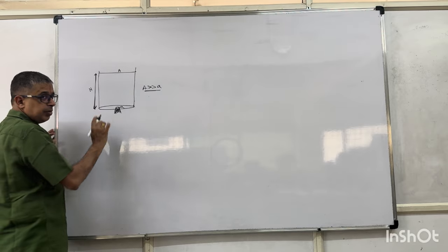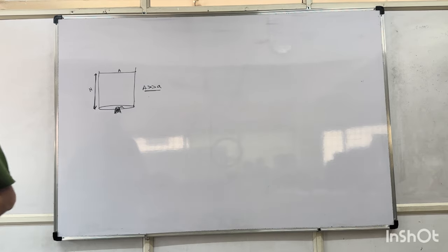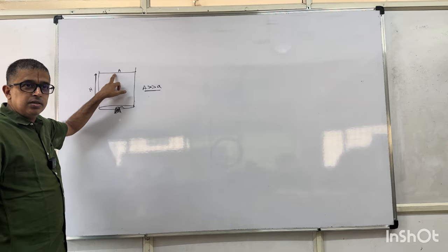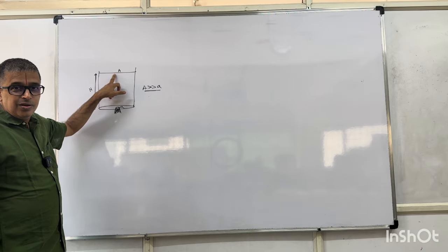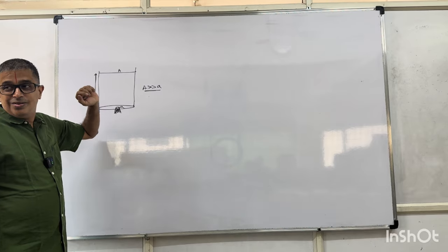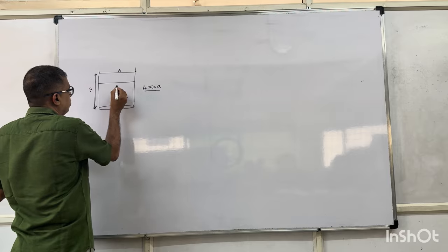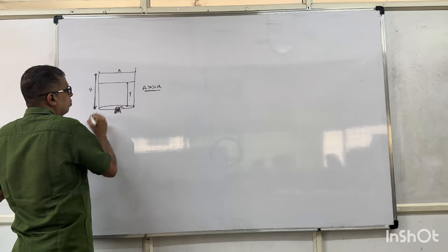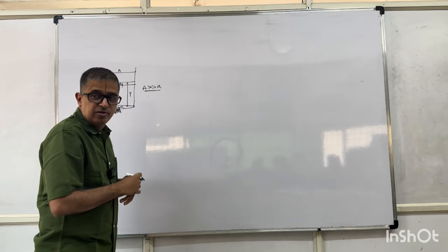That means velocity will be root over of 2gh. Now there is a basic doubt that the students get. If capital A is much greater than small a, that means this velocity you are taking is negligible. That was what you did in the Bernoulli's equation. So it will never get emptied. So this is the logic which students apply. We consider after time t in a short time interval dt, let this height be y, and in a short time interval dt this moves by a distance of dy.